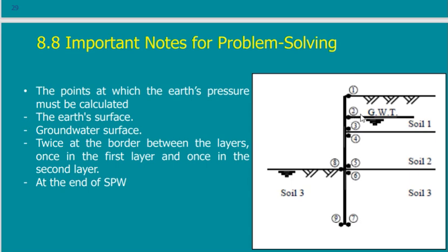There is a point which is 2. In point 2, I calculated values. Why did I calculate values? Because this is the start of groundwater. So this will be the top of the triangle for the water, so I need to calculate at this point. But I don't want to calculate above and below. Above and below is all at layers, start and end of a layer. But if I have groundwater in the middle of the layer, then I will calculate once. All of these are active.